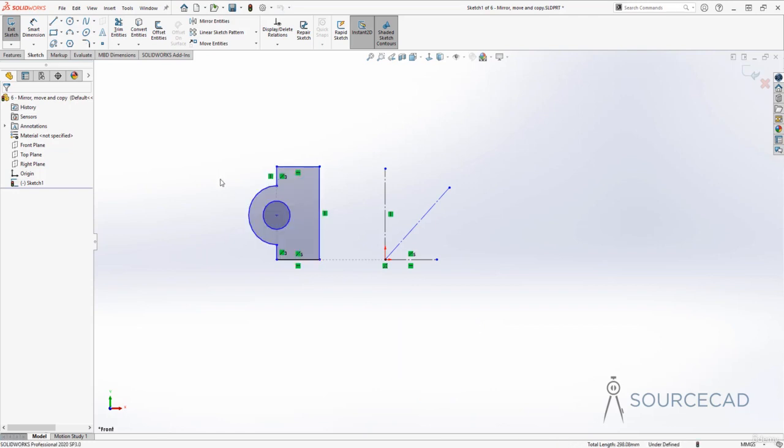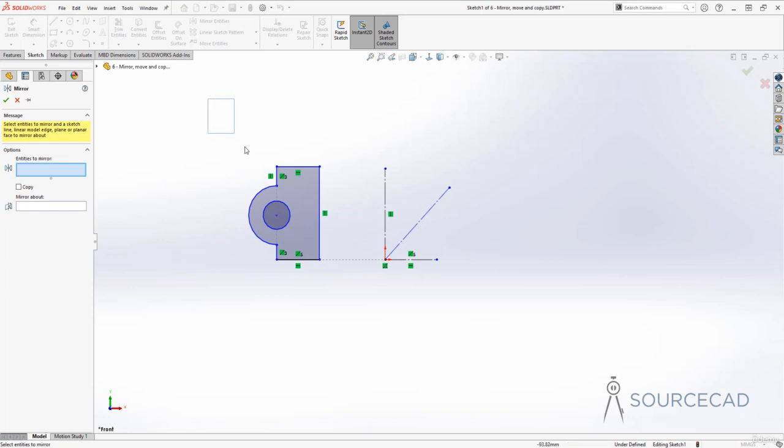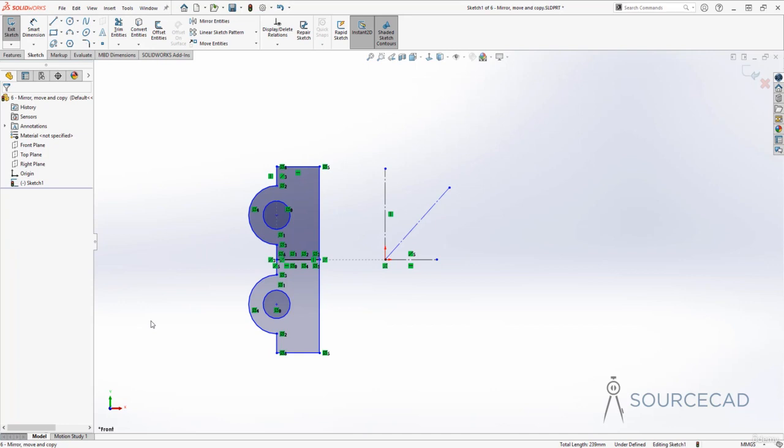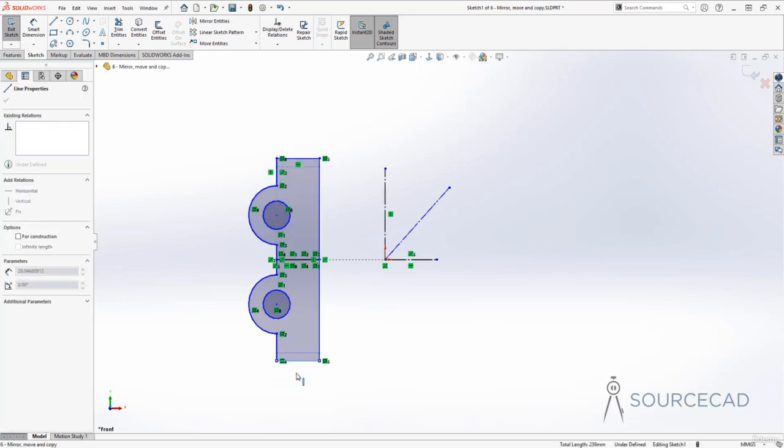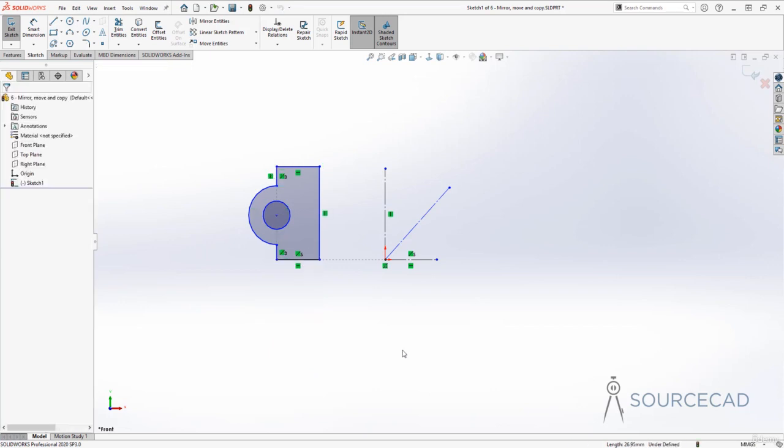Now you can use the existing lines on the same geometry as well for mirroring. So I'll go to mirror entities, I'll select it all, and in the last example I'll first select this copy, and then I'll click on mirror about, and I'll select the same geometry, one of the lines of the geometry, maybe this one, and it will make the mirror image like this. You can even select this line, or any other line of this drawing, and that's the mirror image and its exact mirror replica. So let's press Ctrl Z again.